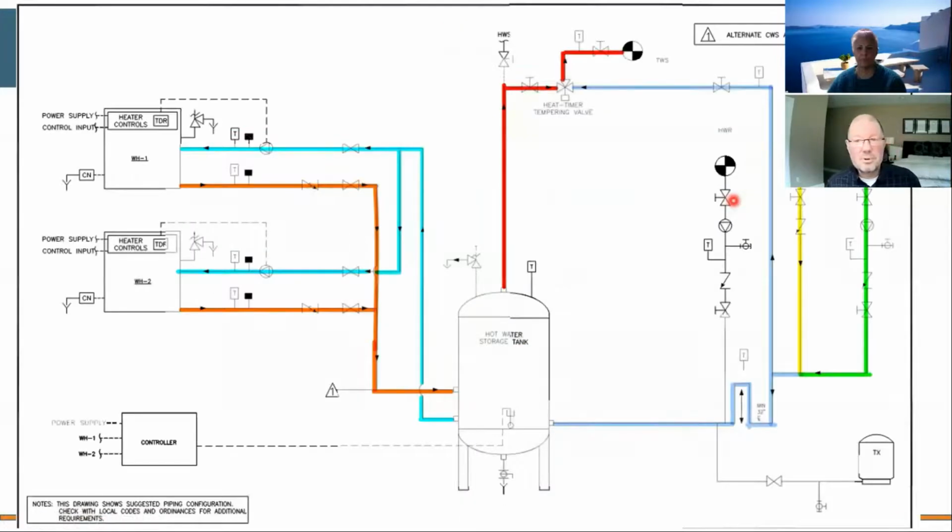Now, another good example, or maybe a better detail, if you will, is sidearm water heaters serving the storage tank. This is how we'd like to see it. And then our cold water and our recirc tied together so that they can either go through the storage tank and pick up warm water to the hot side of our tempering valve, or come up here through to the cold water port where we can mix and maintain tempered water out to our system.